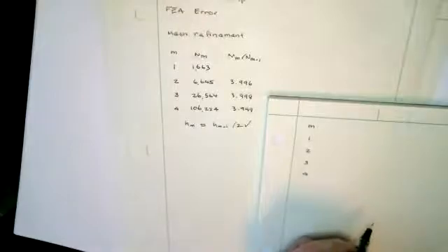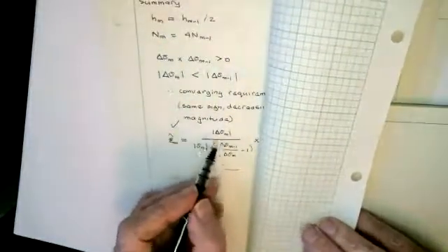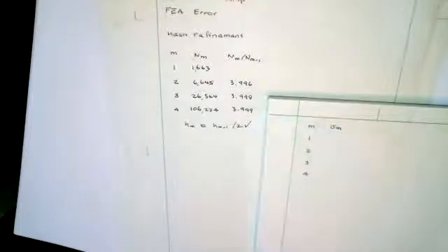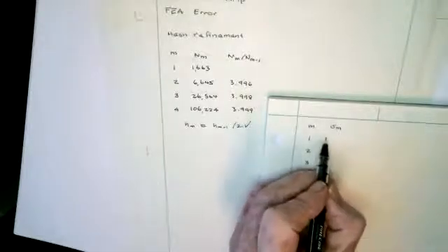Now, normally we're only interested in 3 figures, but to do these stress estimates, we have to take differences. And you want to get the differences, these delta sigma, to three figures. So we're going to have 4 decimal places here. This was under Km there, but it's sigma max divided by sigma norm. Here are the values.